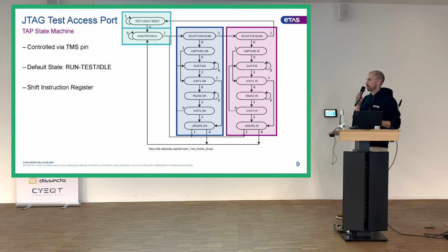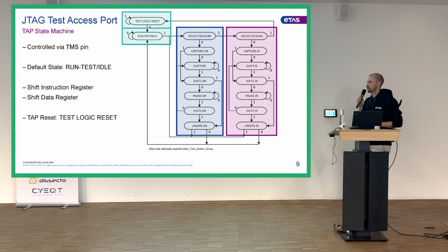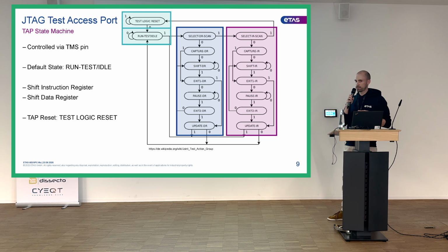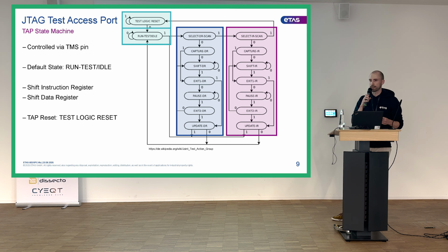There are a lot of states in this. They're not really that relevant, but the same thing exists also for the data register. So whenever I want to change the value or read or write data for any of these 2 registers, I have to go through some of these states. And then, the last thing that I have is the test logic reset state. This only resets the test access port, but not the entire chip. So it's not like a system reset or a power on reset that I can do.